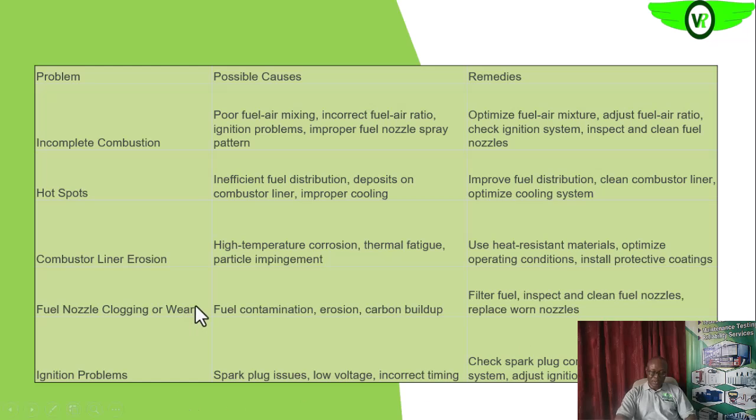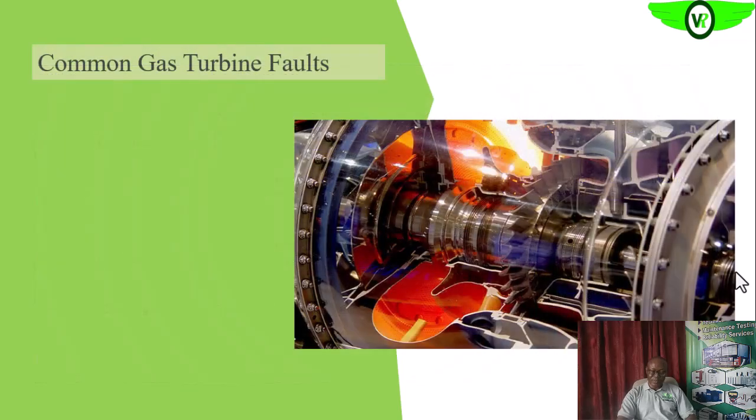Here we see some of the things that can cause clogging: carbon buildup. As the fuel is combusted, if the fuel is not too clean, it can result in the deposition of carbon at the nozzle tips, and that can cause plugging.